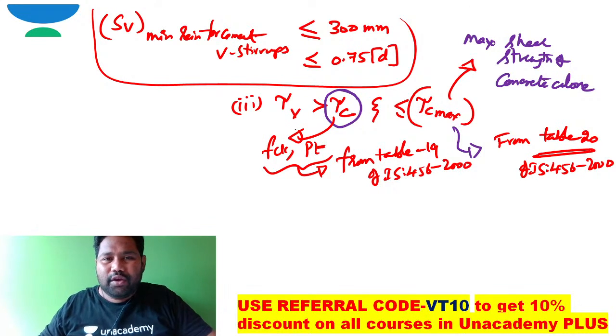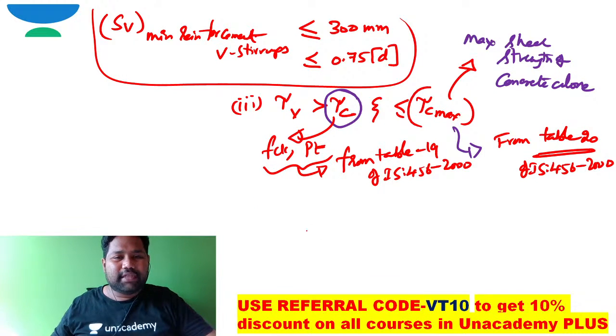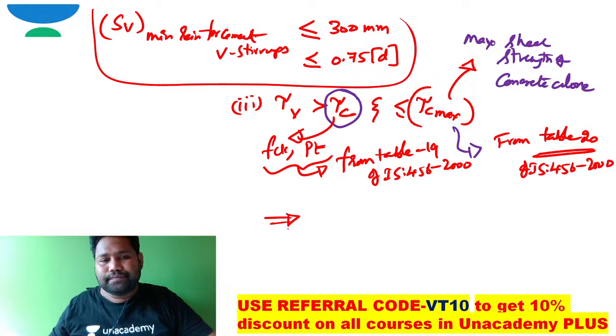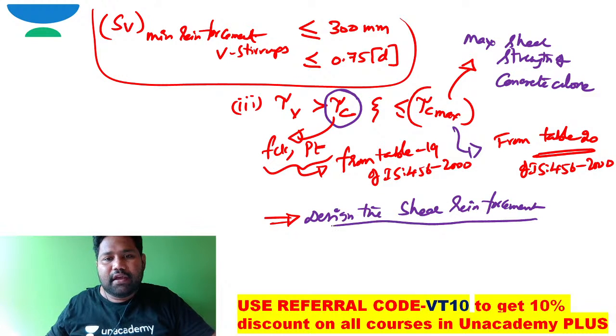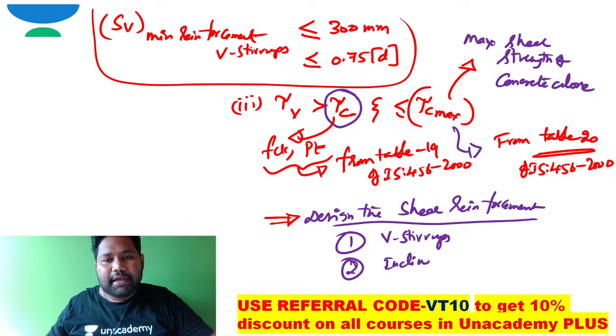So when you do this, here is how to design the shear reinforcement. We can design the shear reinforcement in three ways: one is by vertical stirrups, second one is by inclined stirrups, third one is by bent-up bars.